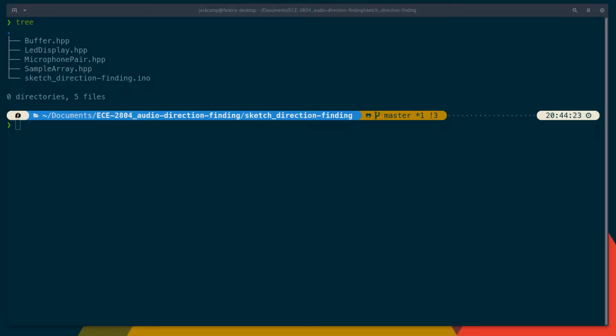The software stage of our pipeline takes the analog input from the first stage, digitizes it, encapsulates it in a nice format to read, uses that to find the phase and then the direction, and outputs that direction in a format that the hardware output stage can use. The software section of our pipeline is an Arduino program which we've separated into several distinct components which we can test separately.